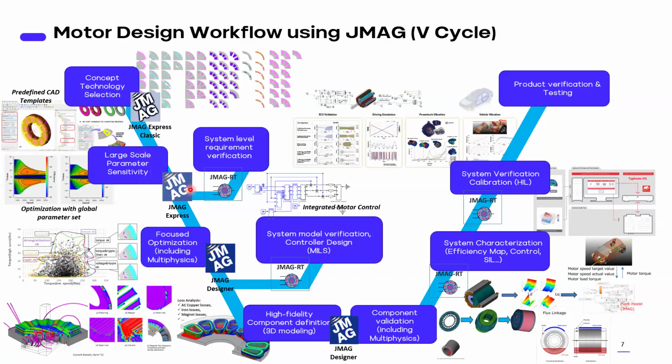After that, optimization with a global parameter set, which includes the Pareto curve, and the best optimized result will be chosen as the output for the motor design. Once it is done, as I mentioned, JMAG-Express is able to directly import the model into JMAG Designer. Once the model is built in JMAG-Express, we can directly import it into Designer for finite element analysis.